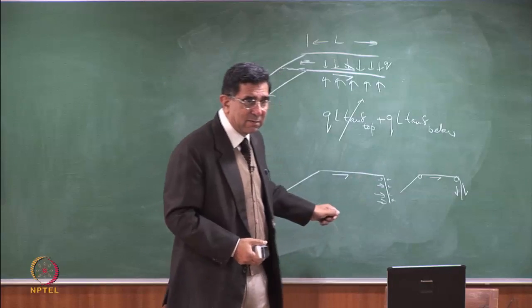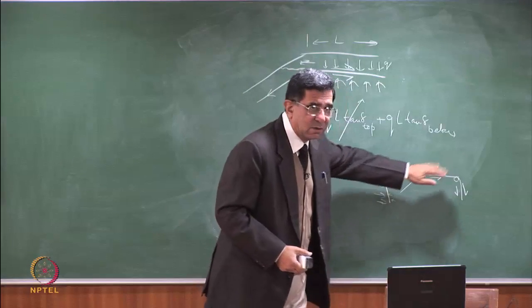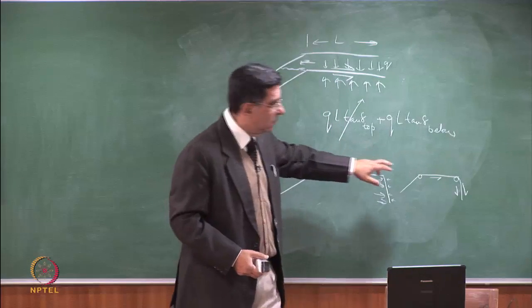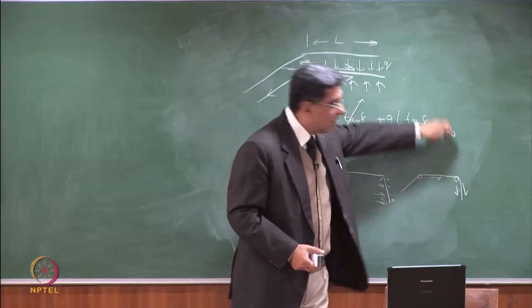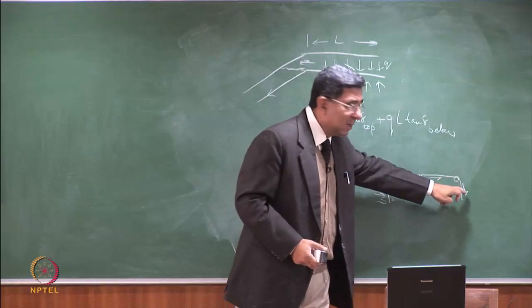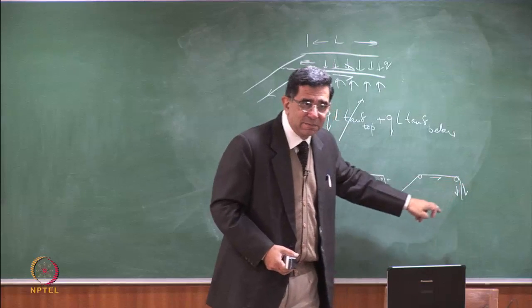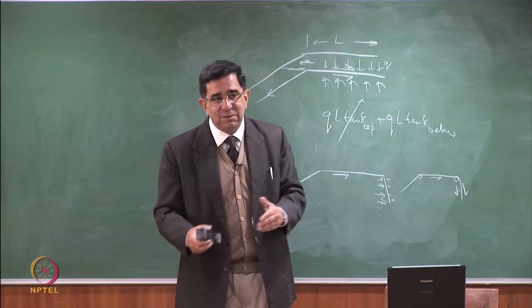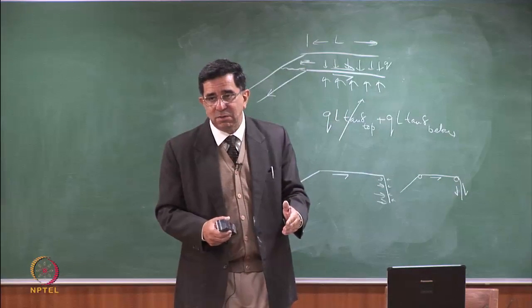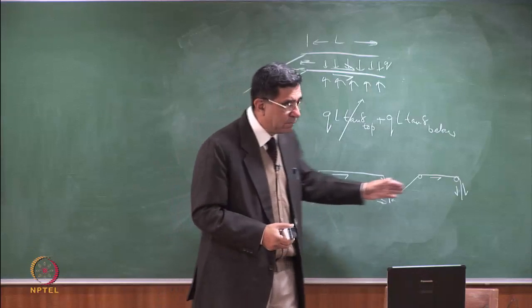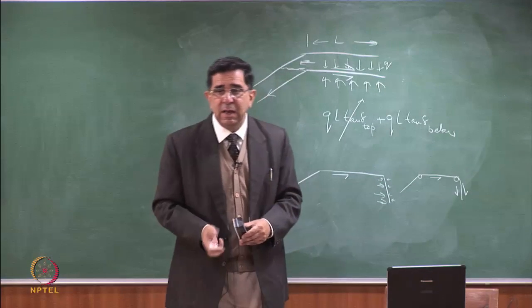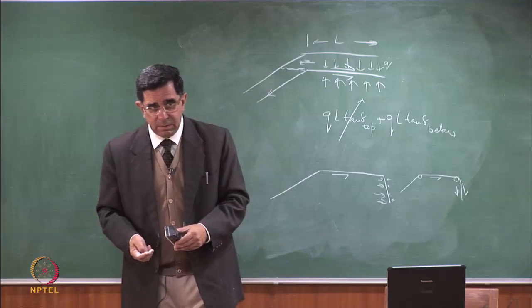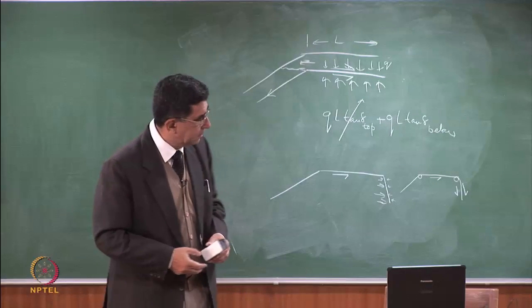You're pulling it, you'll get friction here, the topsoil is moving out with it. There's a frictionless pulley here, this will want to come up. So it will be the P tan delta. There will be friction on both sides of the geomembranes. So these are two different theories, one by Koerner and one by Sharma and Lewis. Okay?